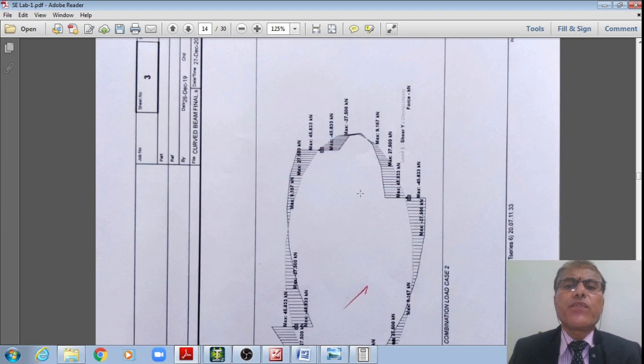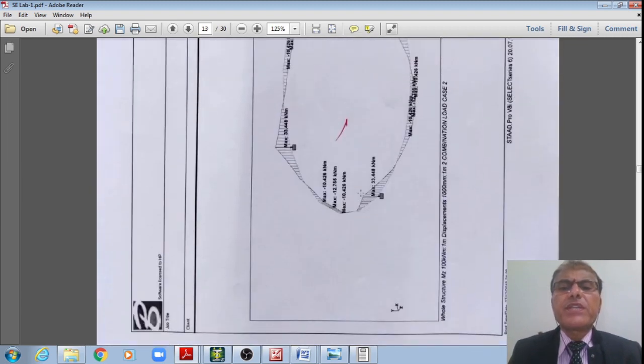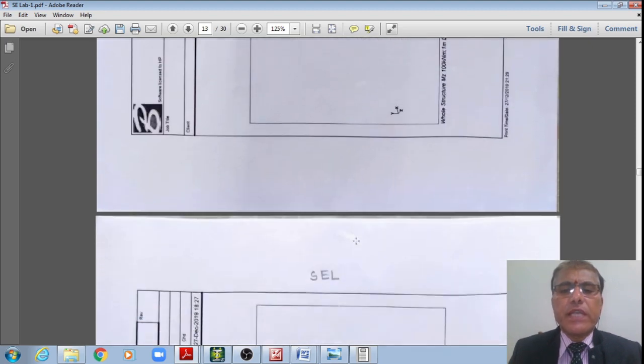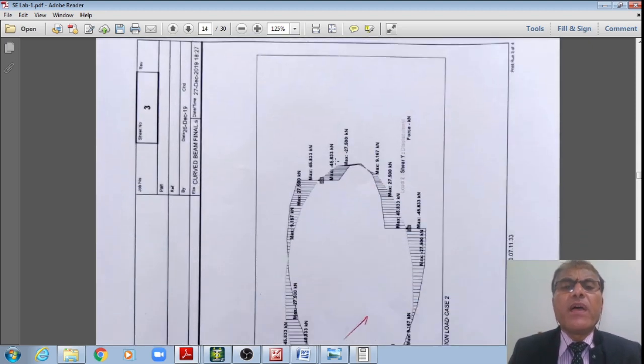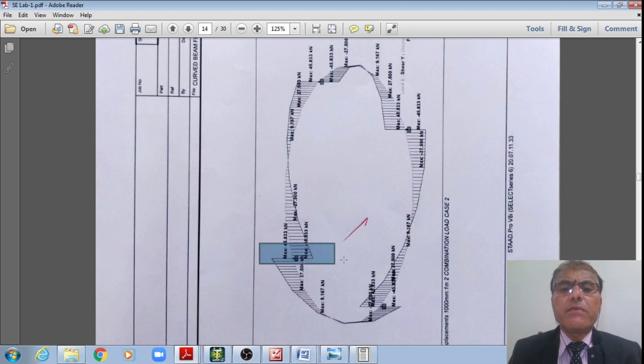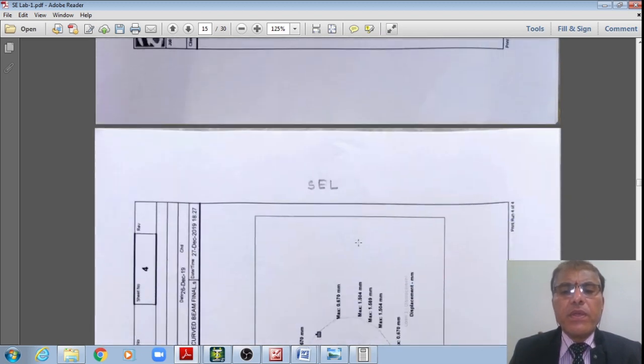This is the variation of the shear force. Previously it was the variation of the bending moment. Maximum 33.462 is the maximum of 33.46, negative bending moment to positive bending moment. And the shear force variation diagram, SFD diagram, this also we have seen, minus 45 to plus 45, and minus 45 to plus 45. That is how we have examined.